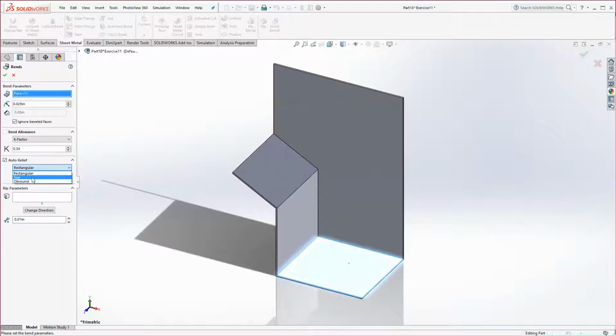And then tear, we used to use that at the company I worked at quite a bit for medical as well as food service. Essentially, instead of leaving a gap in between where the bends take place, it actually just tears it. It's a very tight area. Therefore, organic materials can't get trapped in the corners. Like, for example, if you're using this on a stainless steel countertop, organic materials can't get trapped as readily inside those corners. And thus, we used to use tear quite a bit.